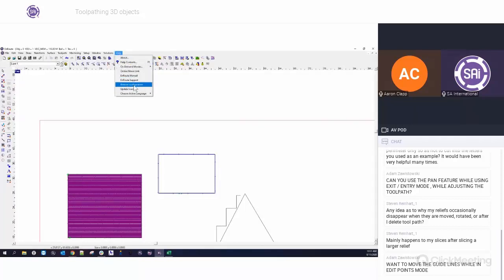So if you have two installs, you can just copy all your settings from the previous version. That way you don't overwrite. If you overwrite, it will delete everything, all your settings, everything. So when you install the update, just make sure to install it in a brand new folder. Maybe call it EnRoute 6 new or something like that when you go to install it, and check and see if that might help.